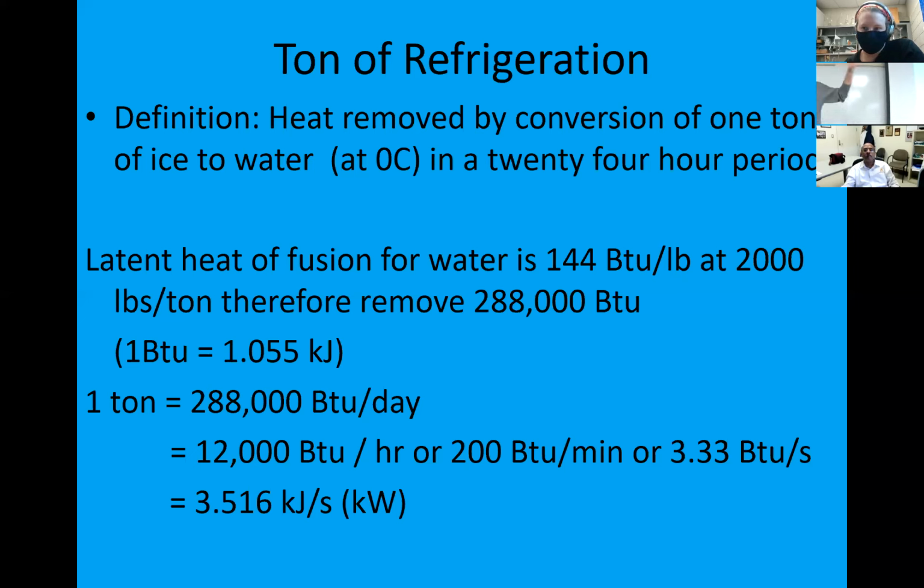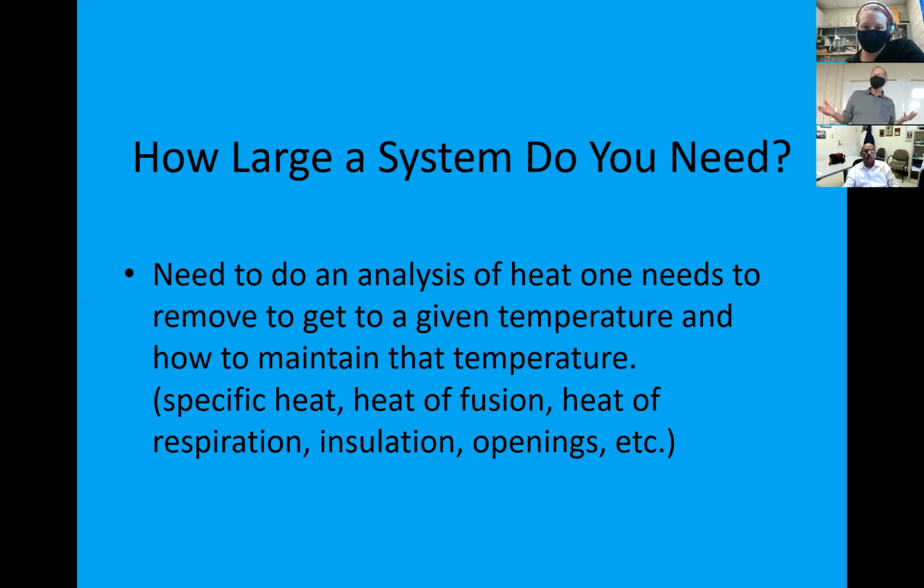That's a lot of background, but the main thing for you to think about as a professional, if you're ever in a situation where you're helping to design a new plant and the refrigeration guys start talking tonnage, is that this is where they're coming from, removing this much heat. But how large a system do you need? That's the question that you'll have to ask.